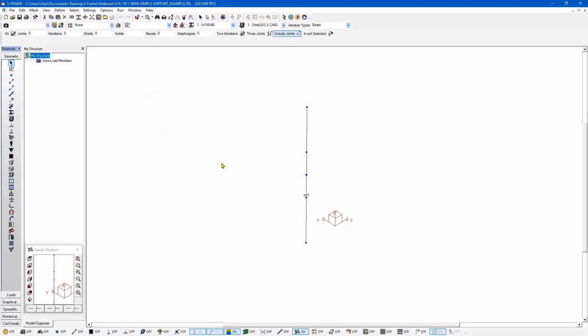Now, one thing you may notice here, if I look at the model, you can see that I actually have these 3 joints within the span of my column. And those are the additional analysis nodes that I was referring to when I was describing those slides. Basically, they help us represent the type of buckling that we might experience, or the type of little p-delta effects that we might experience when we have a little p-delta situation where we have both ends essentially laterally restrained, but the top end can still move vertically. We need those additional nodes in the interior to really describe that behavior.